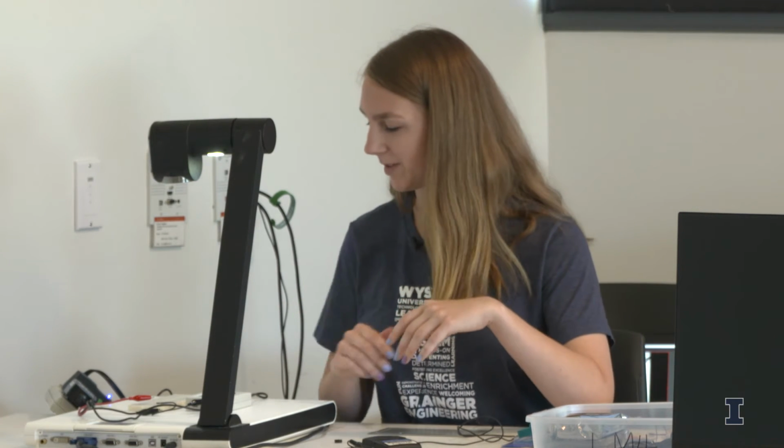You go on 5 seconds, 2 seconds, 1 second, 1.5 seconds, and it's not changing. Still on trigger. Is it on trigger auto? And is it running? Yeah, I'm on the same. Okay, that might be the problem.